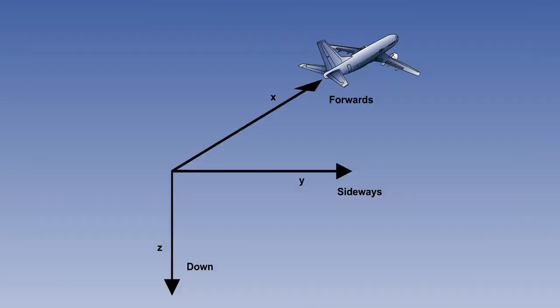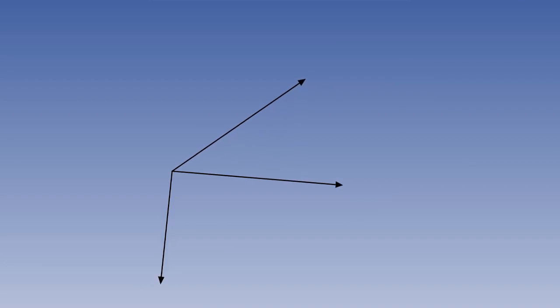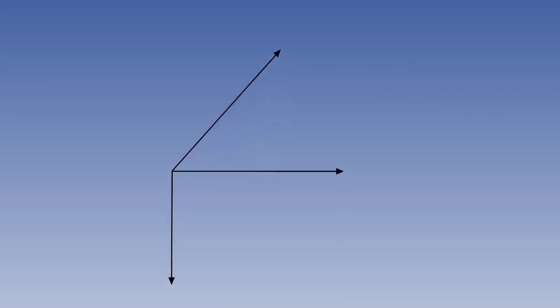Let's summarize the main points from this lesson. There is no gyro-stabilized platform in IRS. Instead, the gyros and accelerometers are fixed to the longitudinal, lateral and normal axes of the aircraft, and they maneuver with it. This is known as a strap-down system. Conversion of longitudinal, lateral and normal axes of the aircraft into the directions of north, east and earth vertical is carried out by a process of mathematical modelling known as axis transformation.